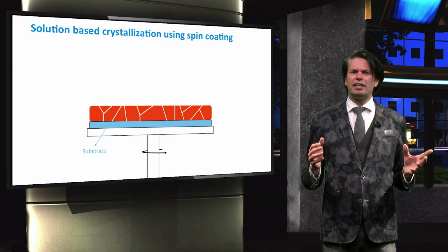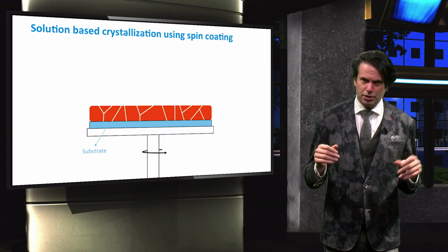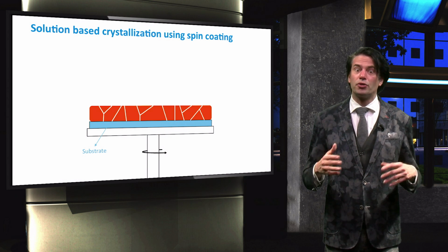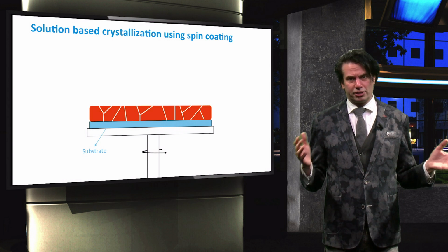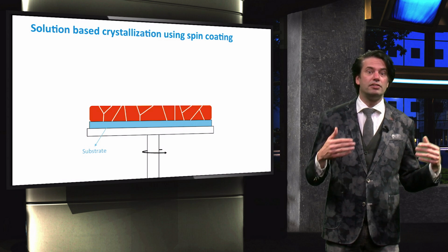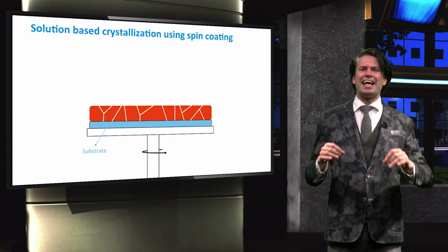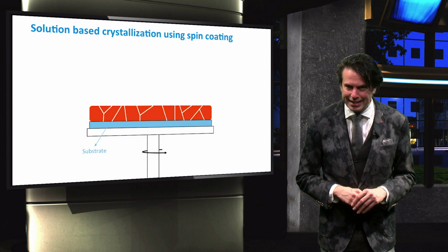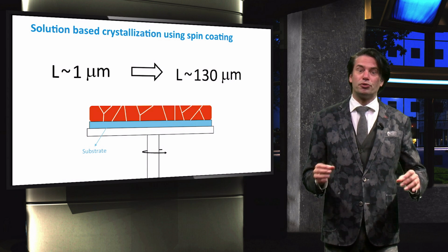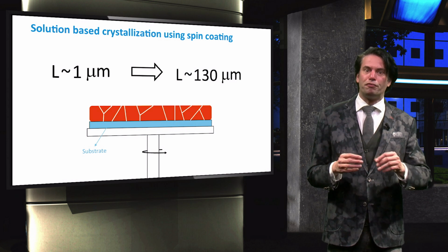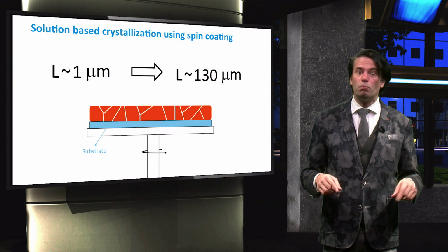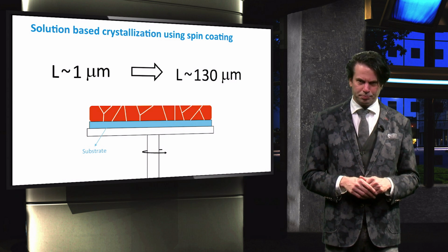The perovskite layer is a polycrystalline layer. This means that the layer consists of grains with different lattice orientations and grain boundaries. As grain boundaries are surface entities in the bulk that facilitate defects, they can enhance the recombination of light-excited charge carriers. By increasing the grain size or decreasing the amount of grain boundary surface, the diffusion length for charge carriers could be increased from 1 micrometer up to more than 100 micrometers.